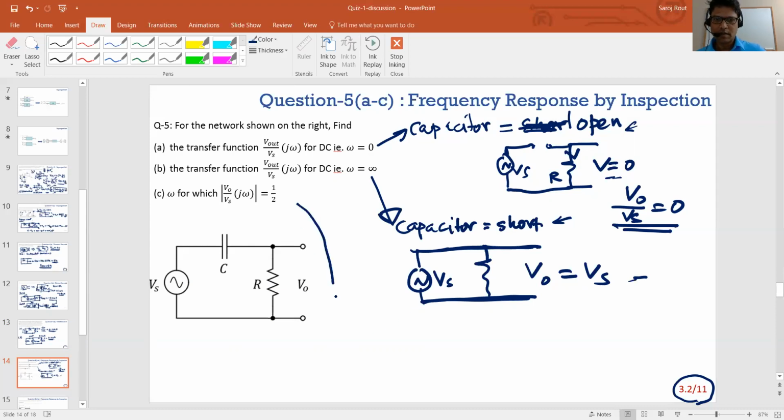The third is you're trying to find out, because there is one storage element, so intuitively you kind of know that there is one pole or a zero. I mean, the zero is obviously coming because of the open capacitor, but the pole is going to be one pole because you just have one storage element, you cannot have more than one. And the way you find out is you say, okay, it's going from 0 to 1, so what's the halfway point, which we usually call in decibels the 3 dB point.